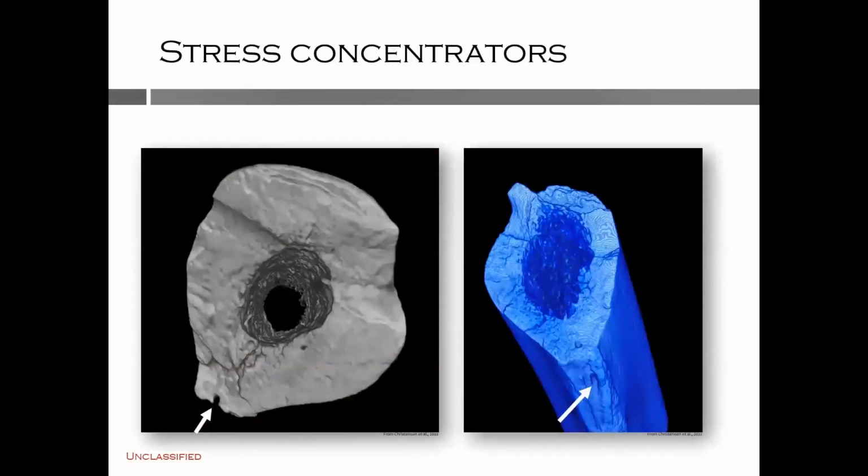In bone, the opening of the nutrient foramen is a pore that can act as a stress concentrator. In a study of bones broken in 4-point bending, the nutrient foramen was found to correspond to the fracture origin in several cases. Other foramina in bones and even openings in cranial sutures may also act as stress concentrators, as can bone pathologies such as abscesses and cysts, or any change that causes a localized weakness.